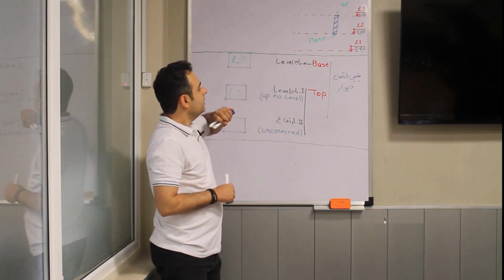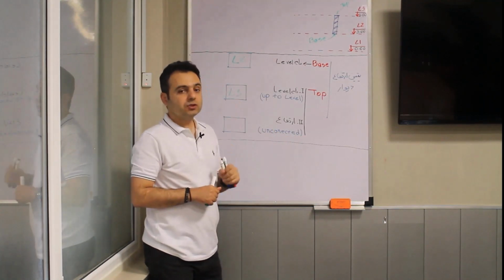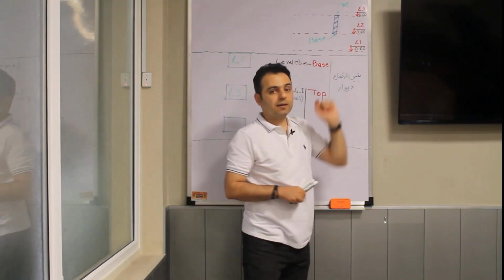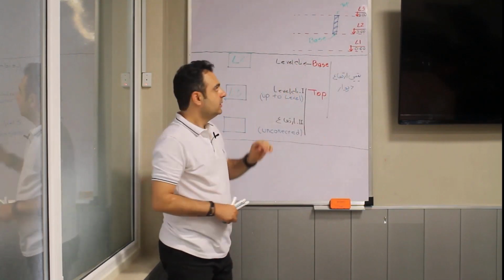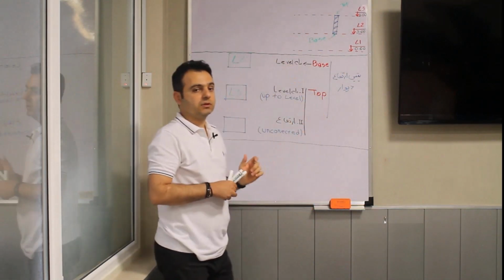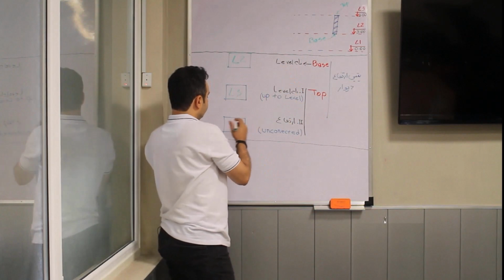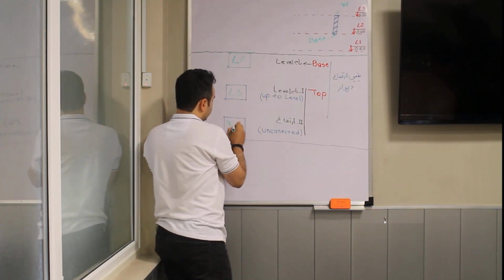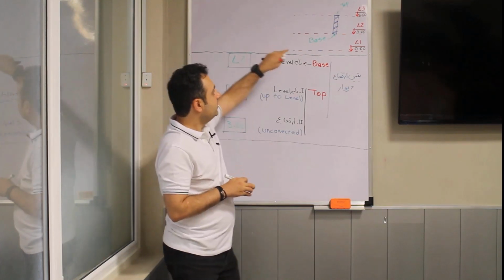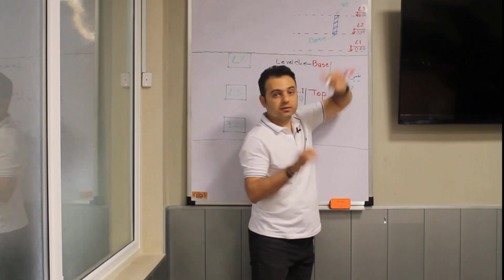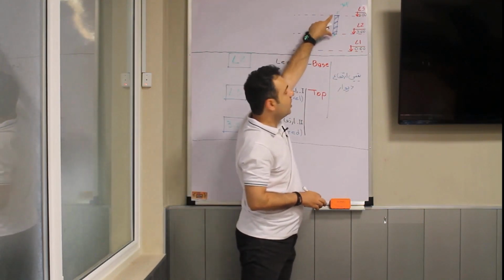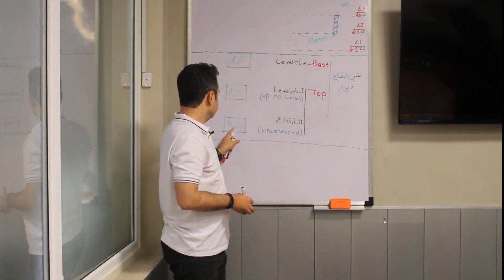Now, if we want to write the height of this wall, what should we write? Now, a lot of you might think that we should say 6, but it's not right, it's wrong. You need to determine the height of the wall itself. So what should we write here? That's right, we should write 3. That means we don't care about the height of the top of the wall, which is 6 now. We should determine the height of the wall, which is 3.